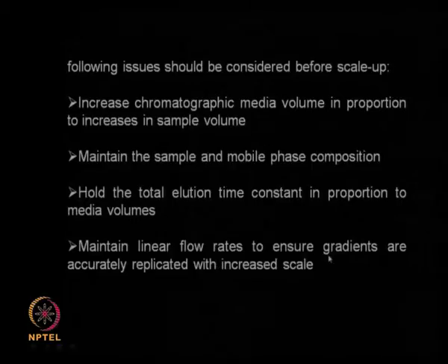I want to maintain linear flow rates so that gradients are accurately replicated with the increased scale. So when I am doing a gradient or a mixture of solvents in small scale, I want to replicate the same thing in the large scale so that there is no discrepancy when I scale it up from small to large scale.